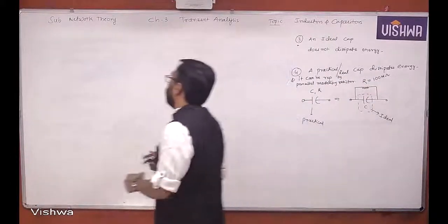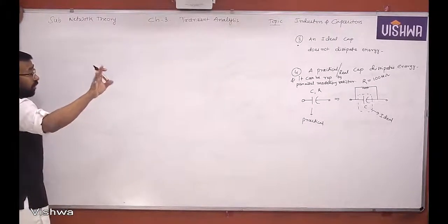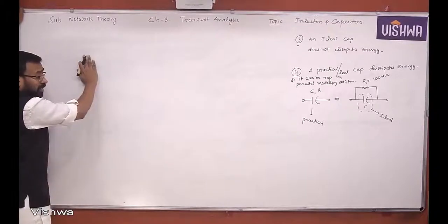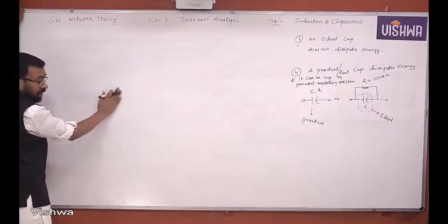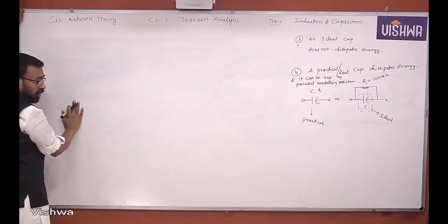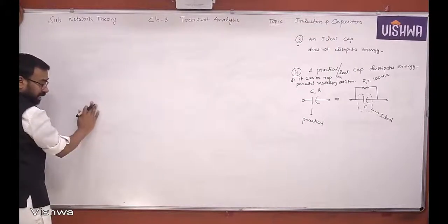Series and parallel combinations of capacitors. First, the four important characteristics one should remember. What is the first one? A capacitor is an open circuit to DC. It blocks low frequency and passes high frequency signals. What is the second characteristic? The voltage across the capacitor may not change instantaneously.